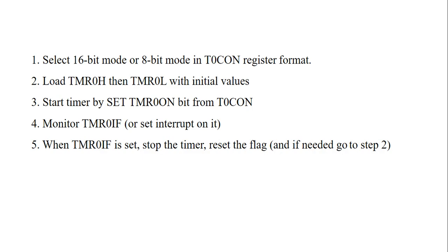When TMR0IF is set, it means the timer has overflowed and the count is completed. Then stop the timer, reset the flags, and again load the count into TMR0H and TMR0L.